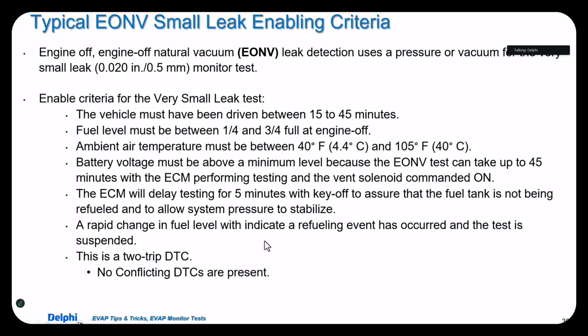This is why EVAP doesn't complete. Those other tests I showed you for gross leak stuff, purge, those work. Those complete most of the time. It's this test with the engine off that can be interrupted, and there's more variables to getting this to run. So that's why we don't complete the EVAP test as often as we should.